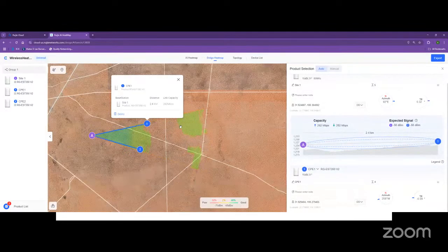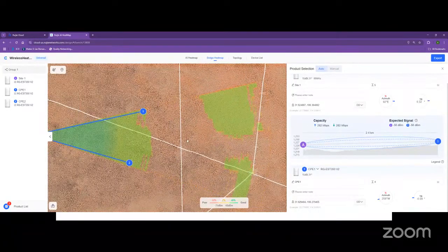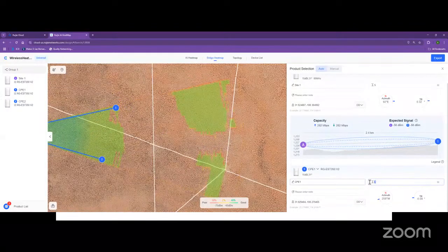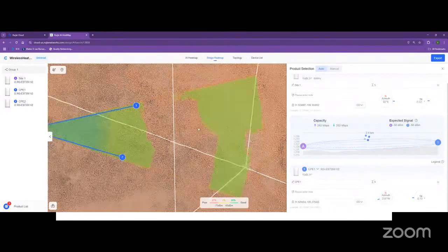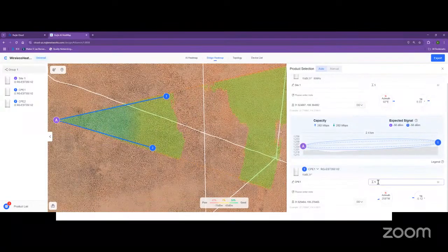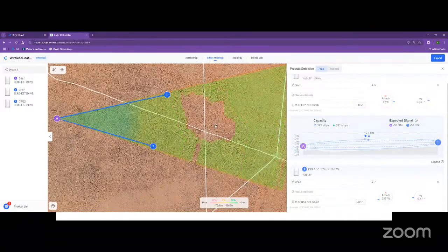That is not convenient. As we can see, the signal, the wireless bridge here, disappears. That is not good, so I need a higher pole. So I'm going to change this to 5 meters. I had changed this to 5 meters, and note that it is not convenient. So I'm going to test 7 meters and let's see what happens.